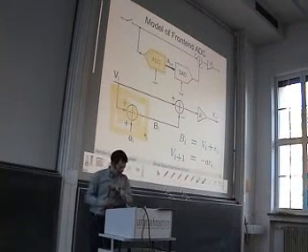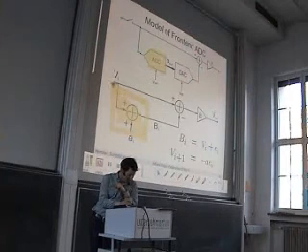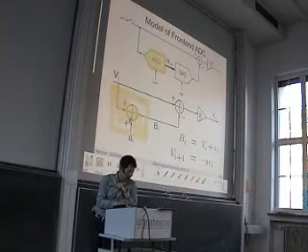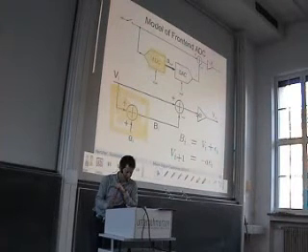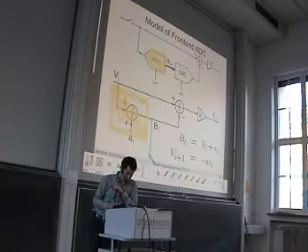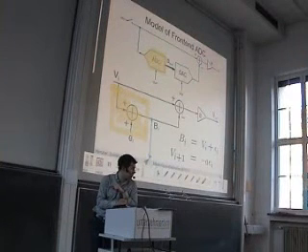Well, here we can see, if we insert this, that we have the input voltage. The ADC is something that adds a quantization error, and this is what we subtract from the input voltage before we scale it back to A. So the output B, so the output of this stage, is given by the input plus the quantization error.